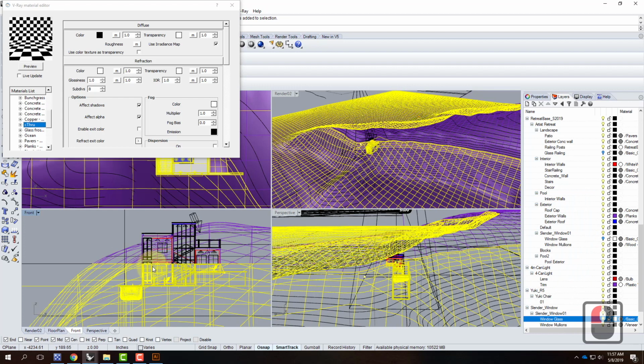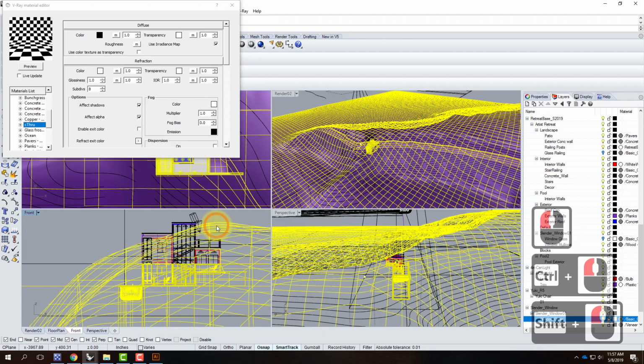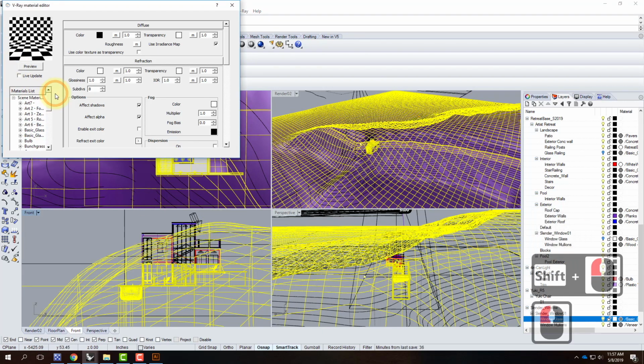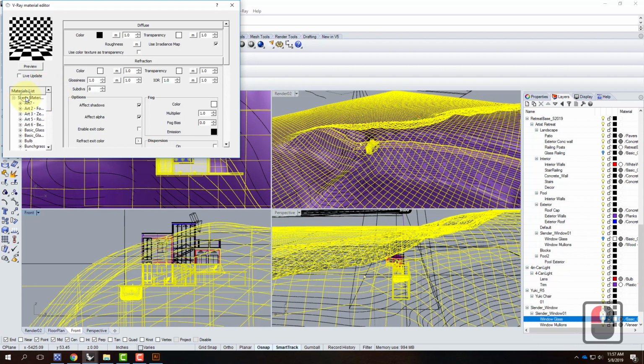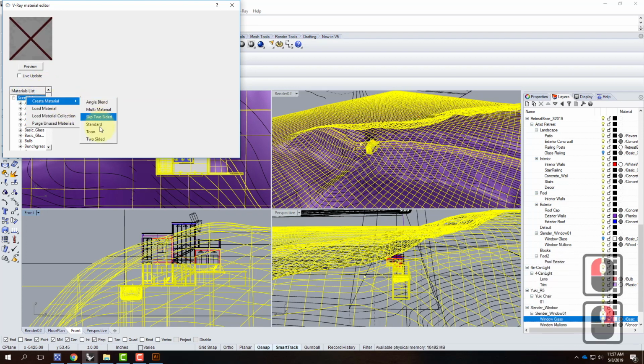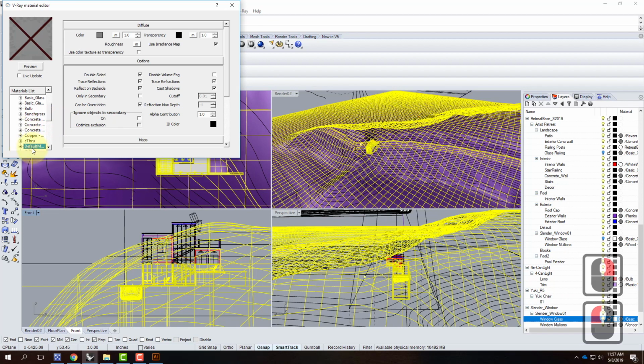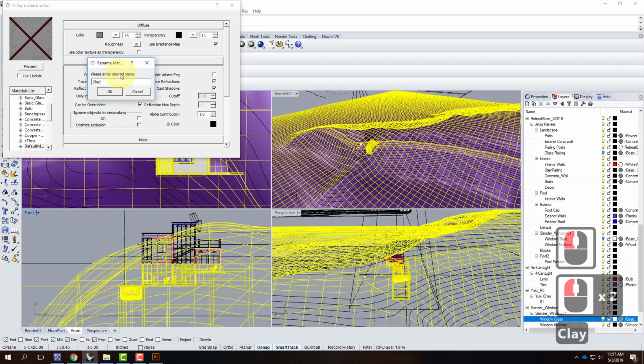All right, there we go. Now I got everything. So all of this plus the terrain up top, so let me hold down Shift and add to that. I need to create a material that's just kind of a plain white, which is essentially a clay material. So I'm going to right-click and say Create Material Standard. We'll rename this material to be clay.